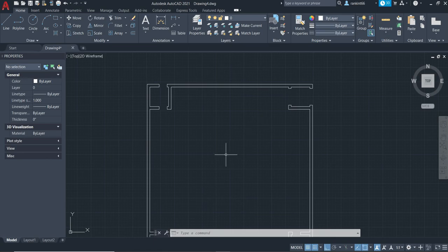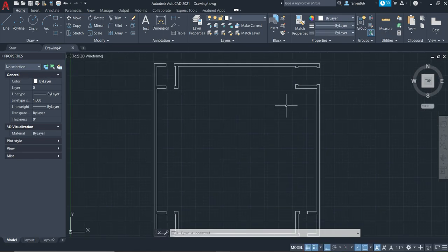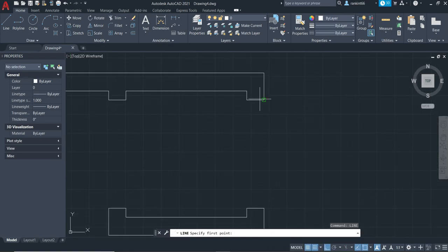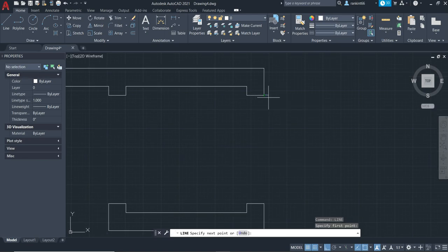The next step that I think we need to do is start adding in our dashed lines to show the doorways as well as our overhang, our walkways of the second floor that would be over top of this. So we want to type in line, enter, and we want to click at these points. Because of my snapping again, I should get a green here, and I want to click here. Then I want to hit escape, and you can hit spacebar now, because if your command is cleared, it will select the last tool.